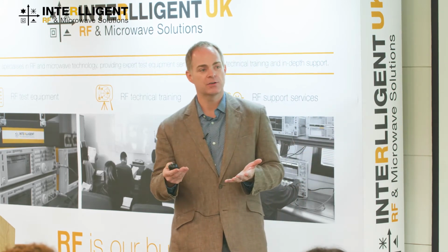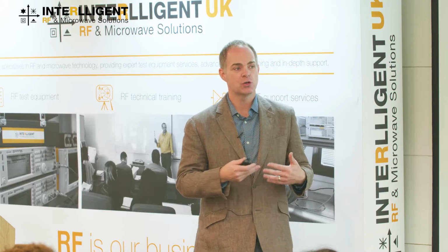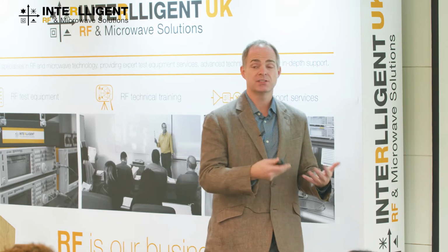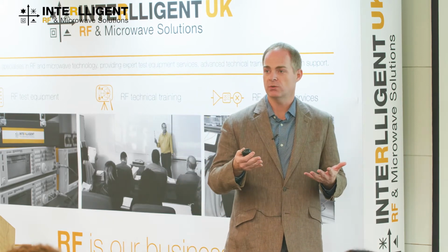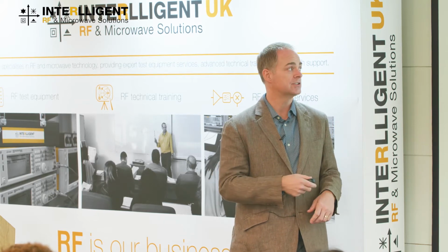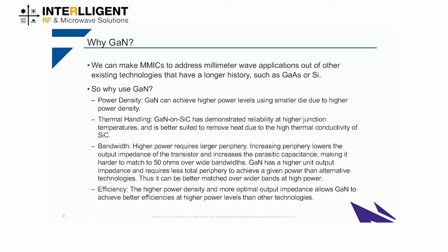As you move higher and higher in frequency, you become more thermally limited just because of how much power you can dissipate and how much heat you can get out, and then also because of the reliability of the devices at those higher temperatures. So GaN intrinsically has a higher temperature threshold and can handle higher junction temperatures than a lot of the other technologies out there. So then you put those two together, and because of the wide band gap nature of gallium nitride, the high breakdown voltages, it allows us to approach higher bandwidth designs at the MMIC level.